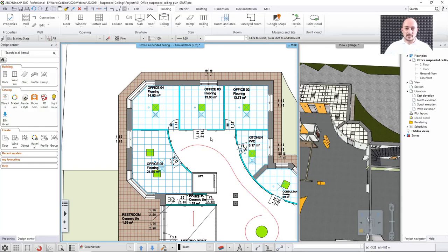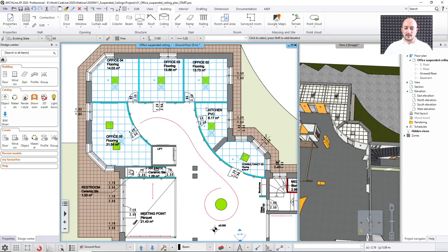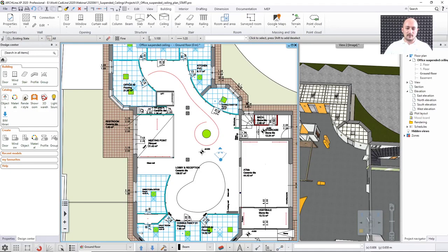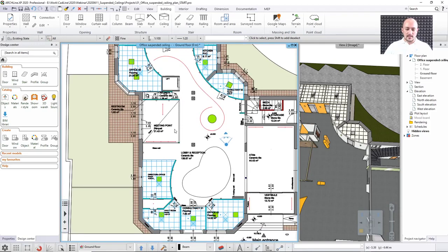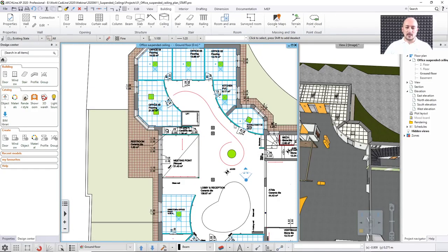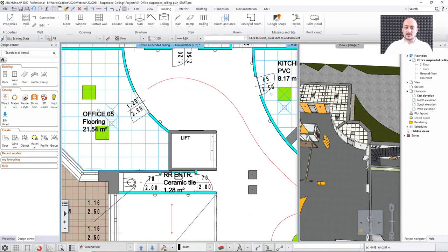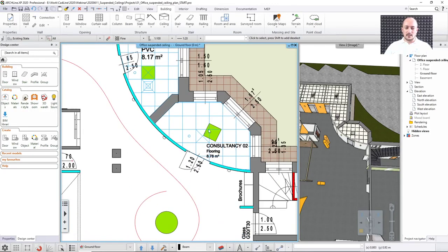Now you can customize the settings. I will show you how to do that. Let's first see what we have here. Okay, that's the first thing. The first problem is that mainly most of the places we are okay, but we have 1, 2, 3 rooms that we need to customize, either because of the alignment or because of the positioning of the grid itself. So let's start here. Here, what I need to do is realign the grid to match this previously defined shape.